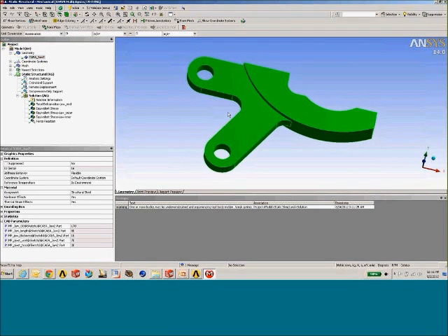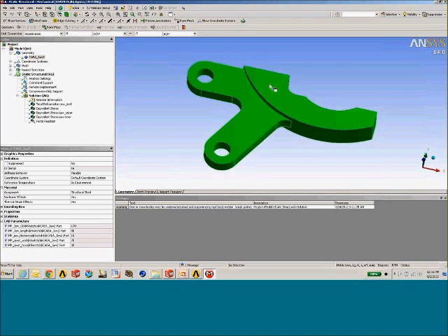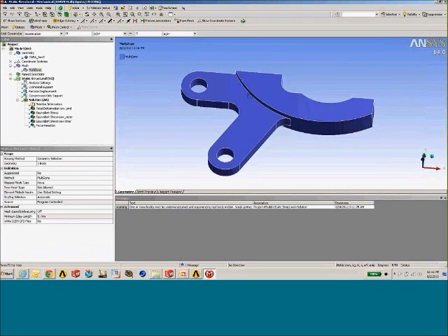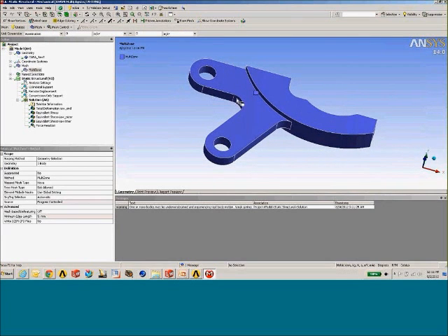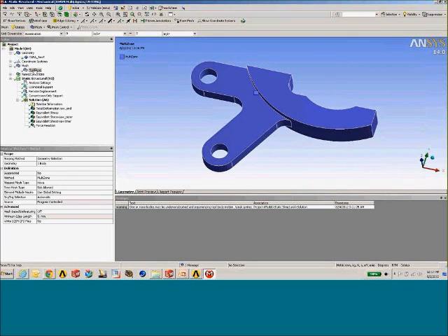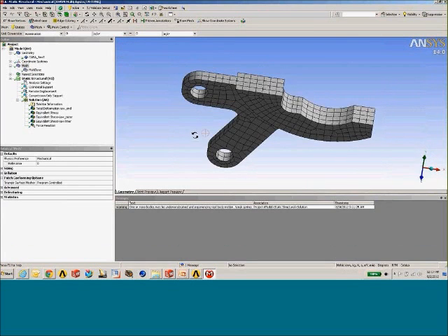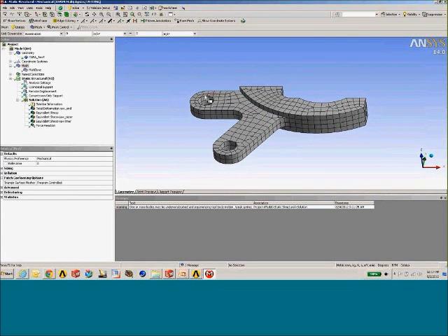So once I've identified those input parameters, now I'm going to go through with this initial design point, and I'm going to make sure that this is a robust simulation. So I want to make sure that I have a sufficient mesh, that my boundary conditions are working correctly, all of the normal due diligence that you would do on a standard type of analysis. So we'll start with the mesh. In the meshing tool, I went and applied a multi-zone control to this particular part because I know the multi-zone will very nicely internally decompose this part into 2 sweepable bodies. And with one single mesh control, I'll get a nice brick mesh on my part.